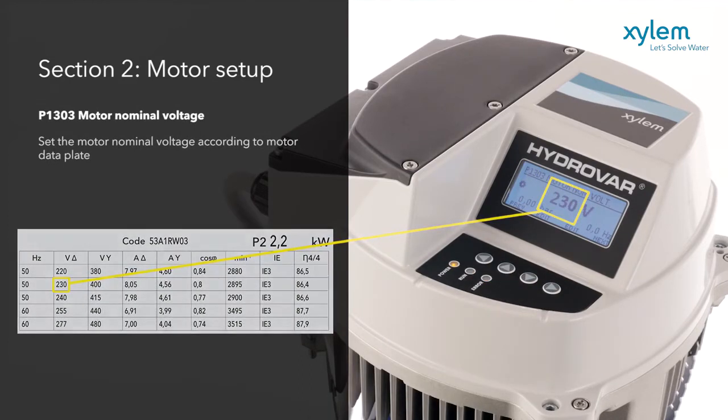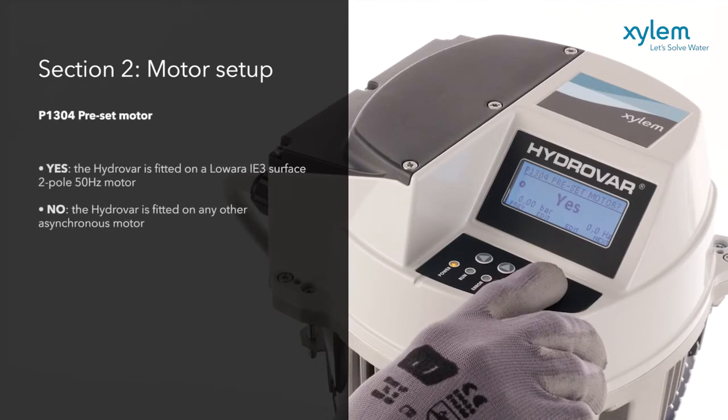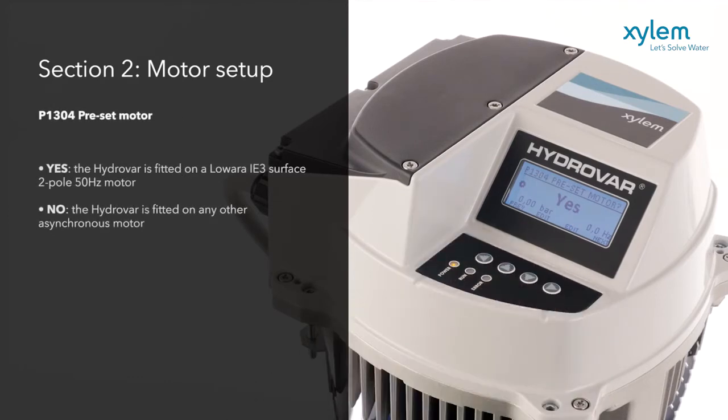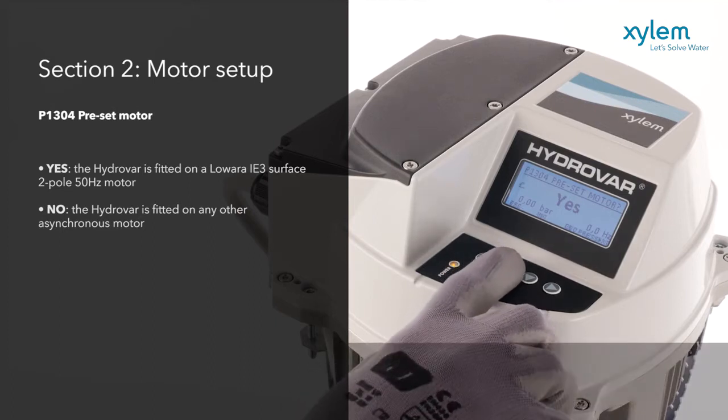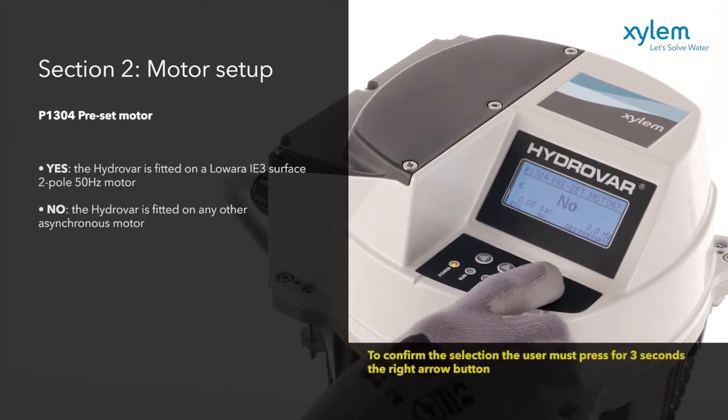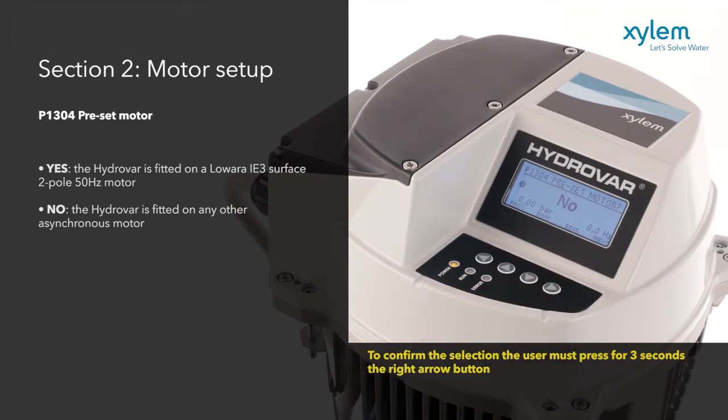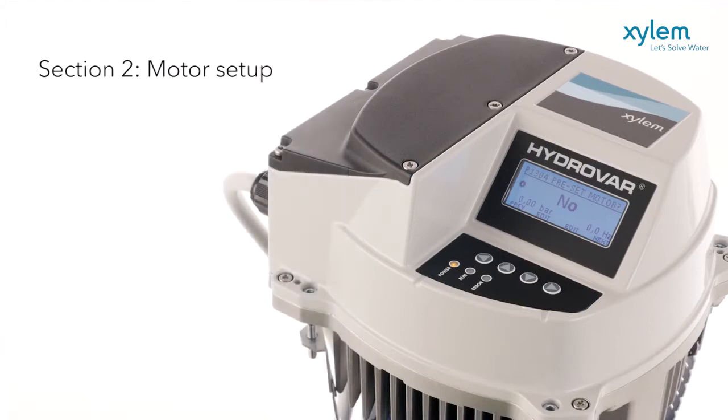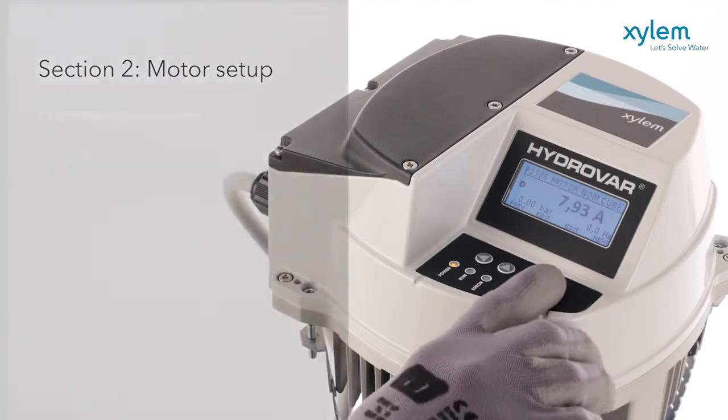Or you can just select the data for a Lowara IE3 2 poles 50 Hz motor, which is already built into the software, or simply select a generic motor. If No is set, additional steps are required to let the Hydrovar identify the correct motor parameters. Otherwise, go directly to the STC thermal protection settings.